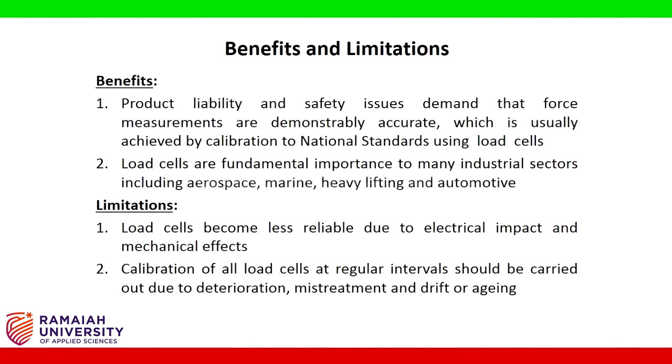Limitations of the experiment. Load cells become less reliable due to electrical impact and mechanical effects. Calibration of all load cells at regular intervals should be carried out due to deterioration, mistreatment, and drift or aging.